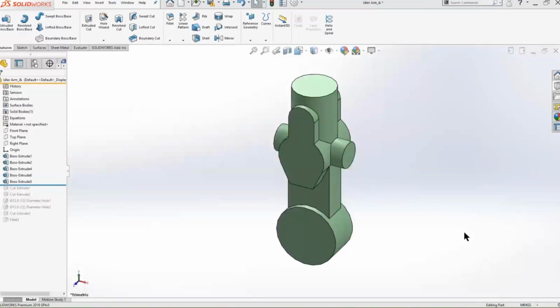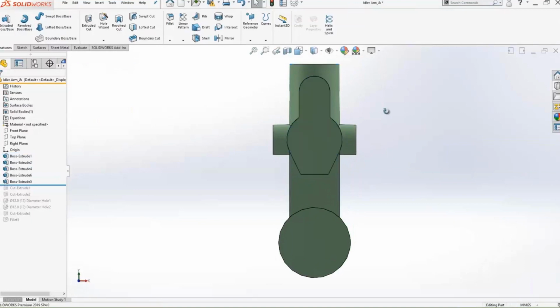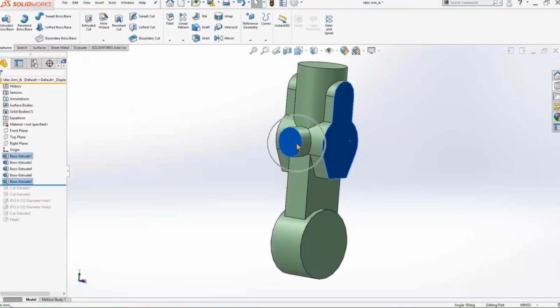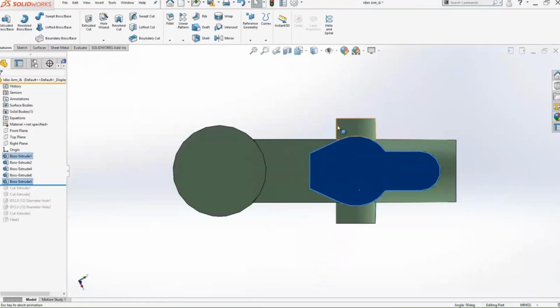The first face you select, the software will reorient normal to. The second face, the vector normal to that face is pointing to the top of the user interface. So let's go ahead and take a look at it here. So normal to, vector. And then once we click it, the software rotates around. So we'll go normal to, and then the little peg is that upwards vector. We have complete control over what's going on there.